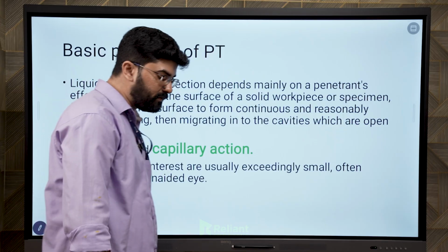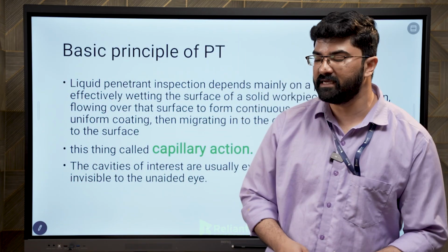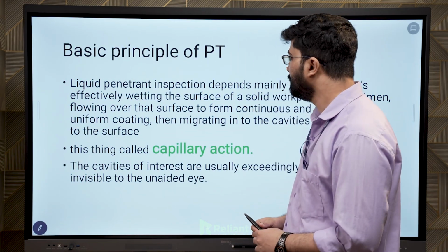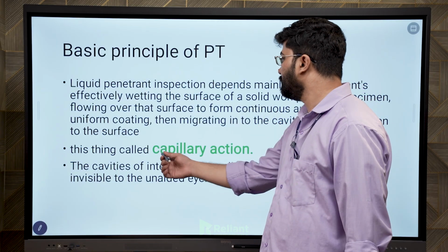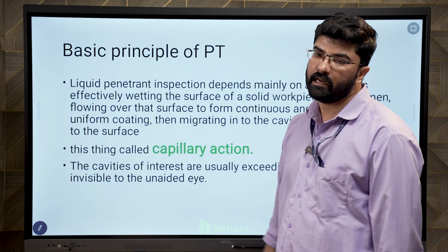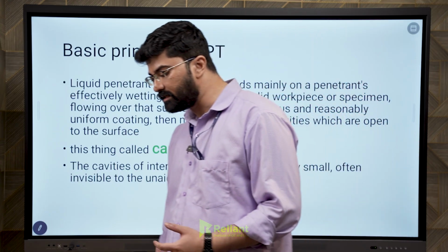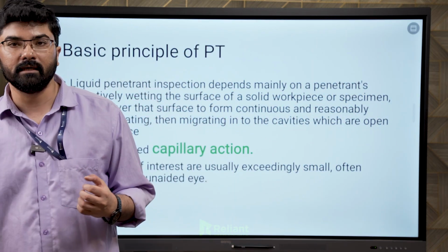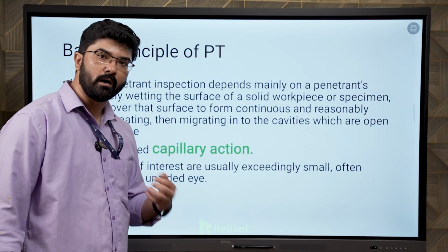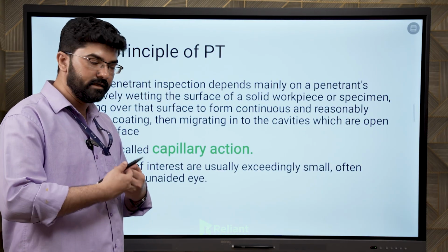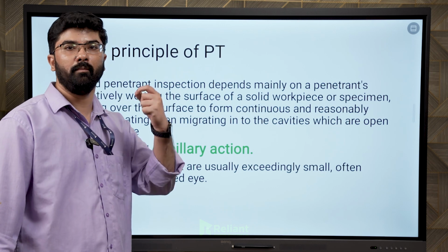So, the basic principle of penetrant testing. What is the basic principle of penetrant testing? Penetrant testing works on the thing called capillary action. So what is capillary action? Capillary action is a property of a liquid by which it can be drawn into a very small opening.